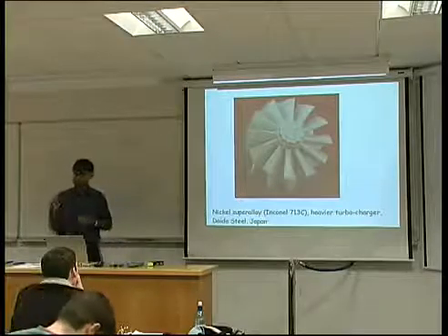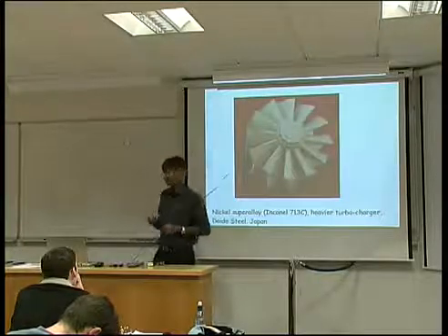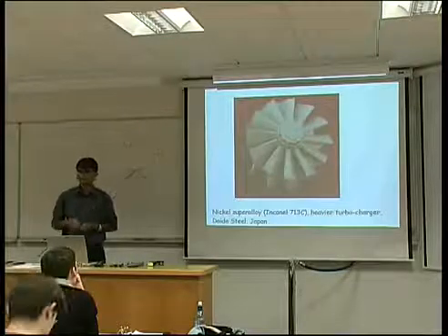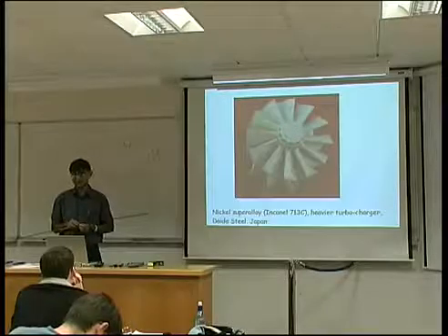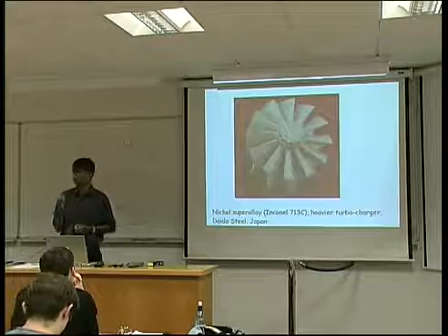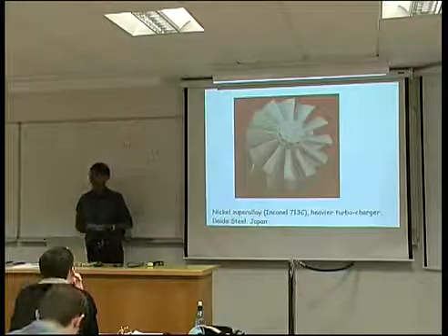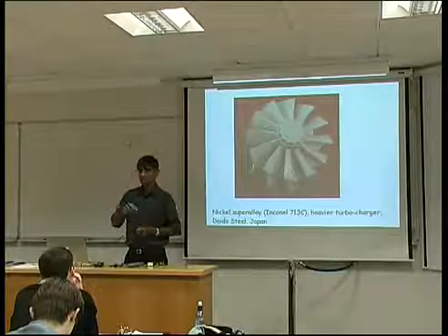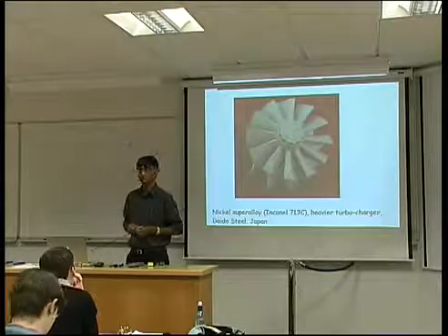So there are some applications of titanium aluminides which are now industrially important and already find applications in very expensive cars. But in general, because of their lack of ductility, they haven't lived up to the promise just 5 or 10 years ago. Okay, so that finishes titanium alloys, and the next 2 lectures I will deal with martensitic transformations. Do you have any questions?